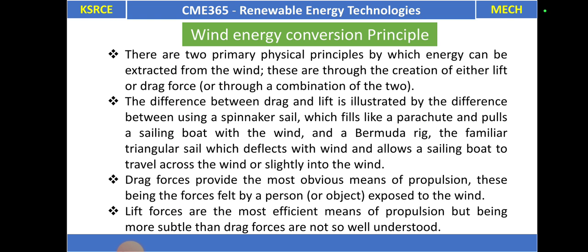The lift is produced by the change in velocity of the airstream, which speeds up the air flow, thereby creating a pressure drop. The pressure drop forces the lift surface from the high pressure side to the low pressure side of an aerofoil. If the pressure increases on the low pressure side, enormous turbulence is produced, which reduces the lift force and leads to a significant increase in drag, called stalling.